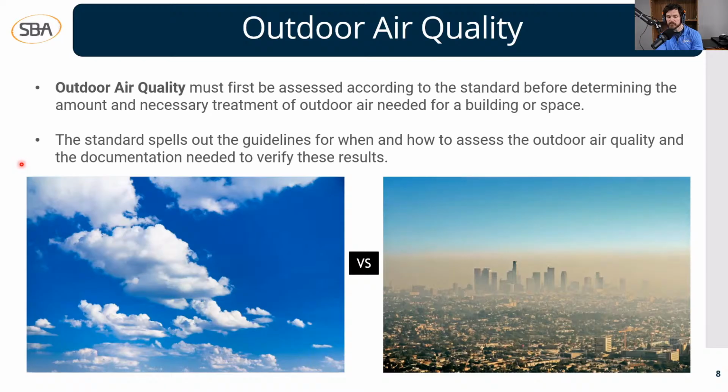And ASHRAE 62.1 doesn't just recommend that assessment, it requires it, especially when you're using the ventilation rate procedure, which is a method we'll talk about more later. Now, always verify the air before you design it, because if your intake strategy starts with contaminated air, no amount of airflow is going to save your indoor air quality.